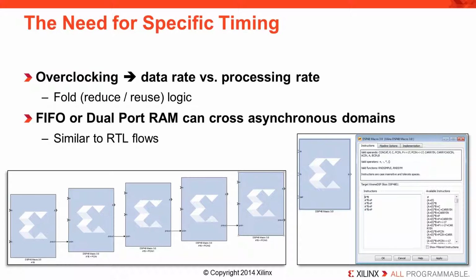But different cores have different maximum operating frequencies, so the overclocking for one section may not be advantageous for another section of the DSP system. In the RTL world, you could run each section at a different rate, each specific to their needs, with minimal handshaking or FIFOing between blocks to get the most out of the system.